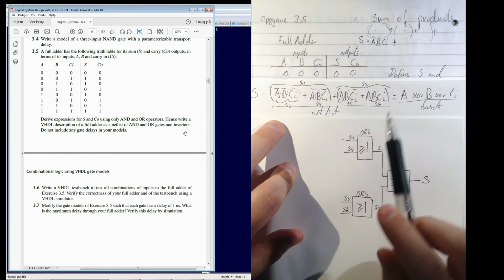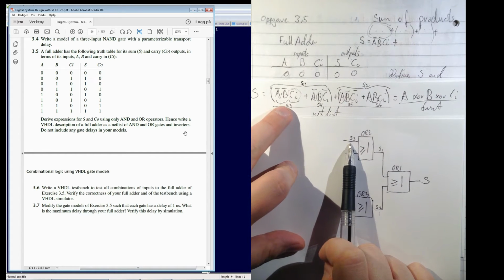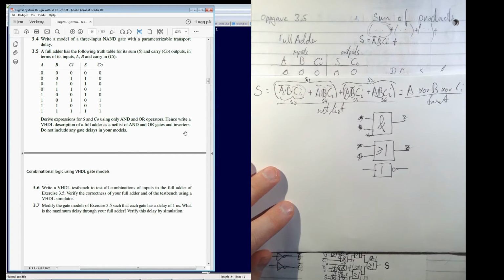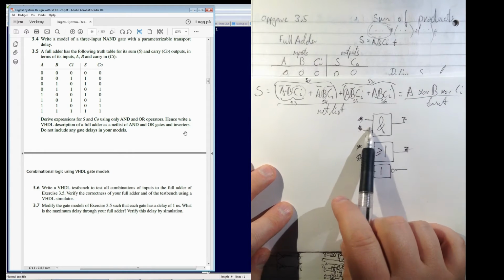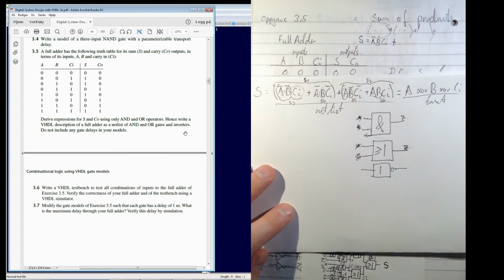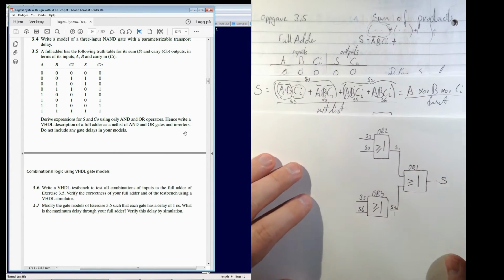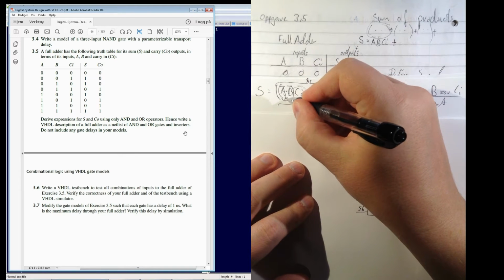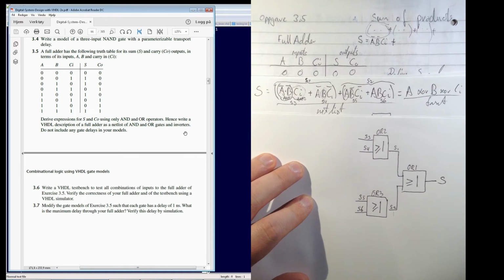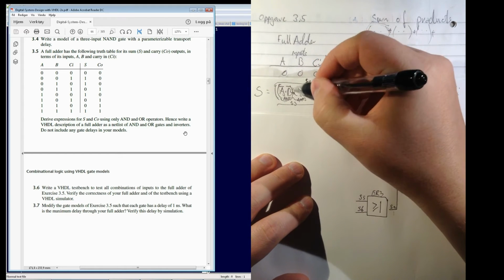Yes, and now let's look at S3 alone. Well, we don't have 3 input AND gates. We only have 2 inputs, so we have to split it in 2, like this. So that will give us AND1 and then AND2, and the gate names anyway. So we need an AND gate that splits this one in two.